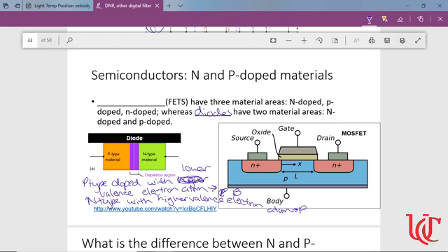The one we saw in the video, though, was a more complex form than just our diode version of that. We have 3 regions of doping. So we have, for example, here N-doping, P-doping in blue, and then N-doping again. And those 3 regions, along with what they're attached to, and we'll talk about those, make up what's a transistor, or a FET, which is a field effect transistor.